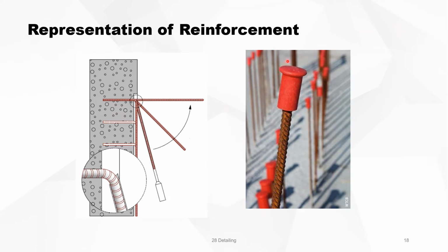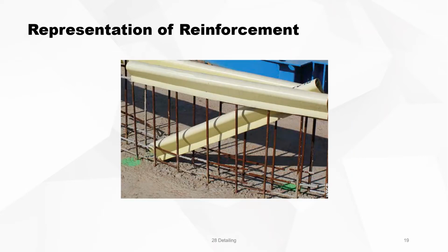This is for safety on each side. You should never have protruding rebars sticking out somewhere where it can hurt people, so you always should have a protection element on top of it. You can have also protection elements like this, and it's a typical element.